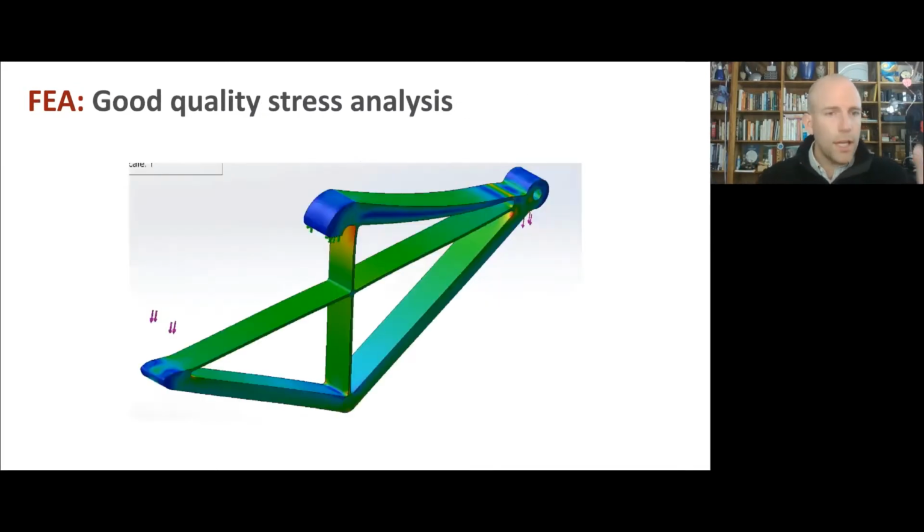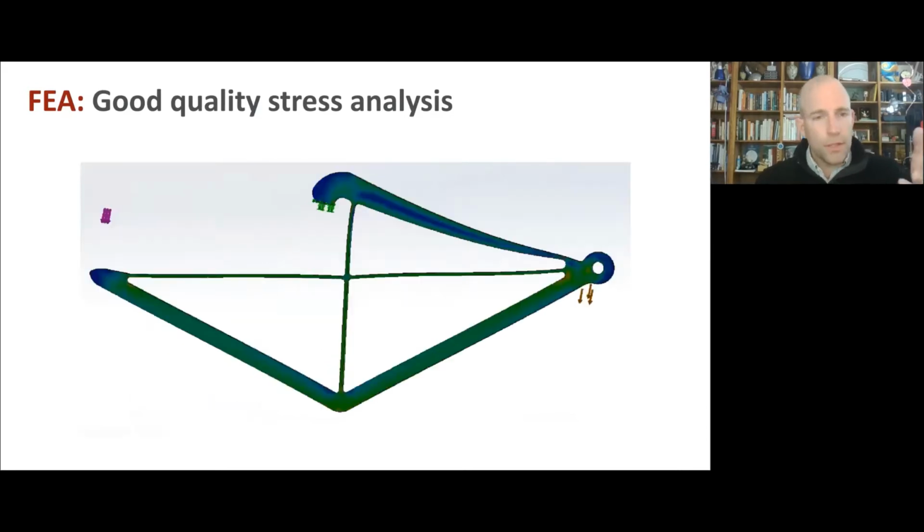And so if you put that together and start to work on the details and refine it a little bit, you end up with something that looks a bit like this. And here you can see this nice, even distribution of stress on these central straps. That's good. And we can fine tune the thickness of the thing to get that just right and avoid having too much mass there. These ended up being pretty short in one direction and a little taller in the other direction because of the primary buckling mode. So here you can see how when this top part bends, it's not pulling out away from the table as much.